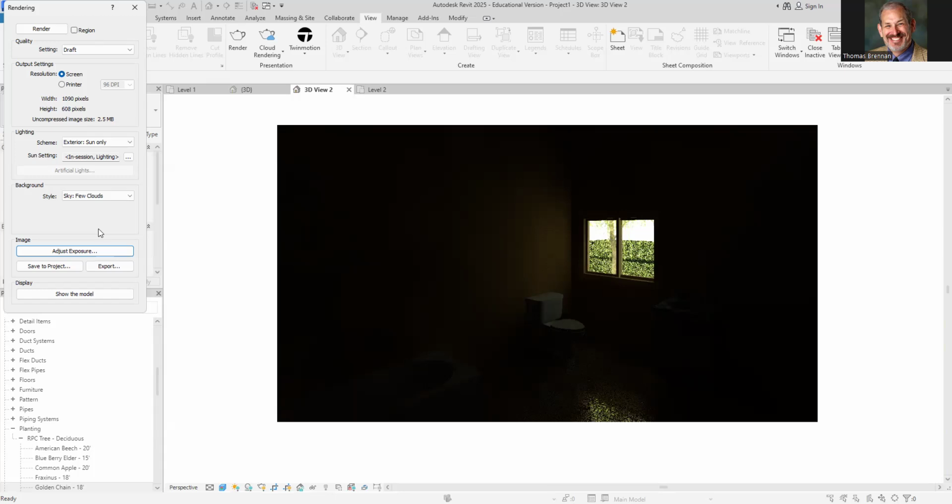Before I do that, how do I add the grass? Good question. Go to floor, and go to floor architectural, and go to your types. That's actually your grass. Then you choose your rectangle tool. Something nice, a little close. Okay, and hit your little check mark.